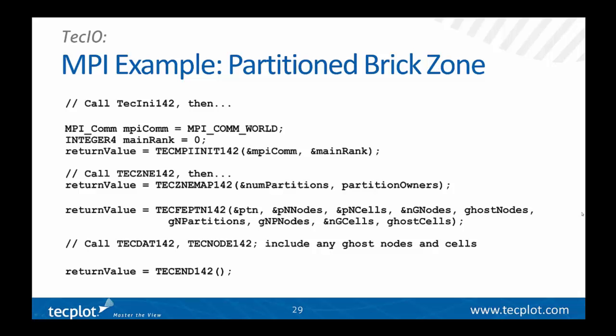Yeah, I think the other thing you would potentially lose is the actual node numbers, because we actually do reorder and renumber the nodes and cells as we do the domain decomposition to create subzones. So what you would want to do in that case, if you need that information, is actually write a variable, an integer variable. Well, I guess it'd be float in this case. Yeah, right. That would be the number of the node, and you can do the same thing with a cell-centered variable, which is the number of the cell, and then you can track what your node numbers and cell numbers are. Okay, thanks.